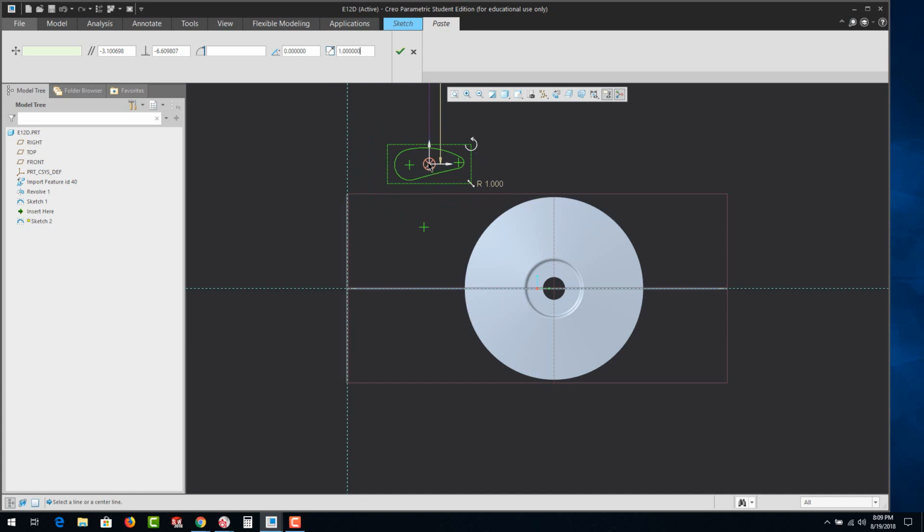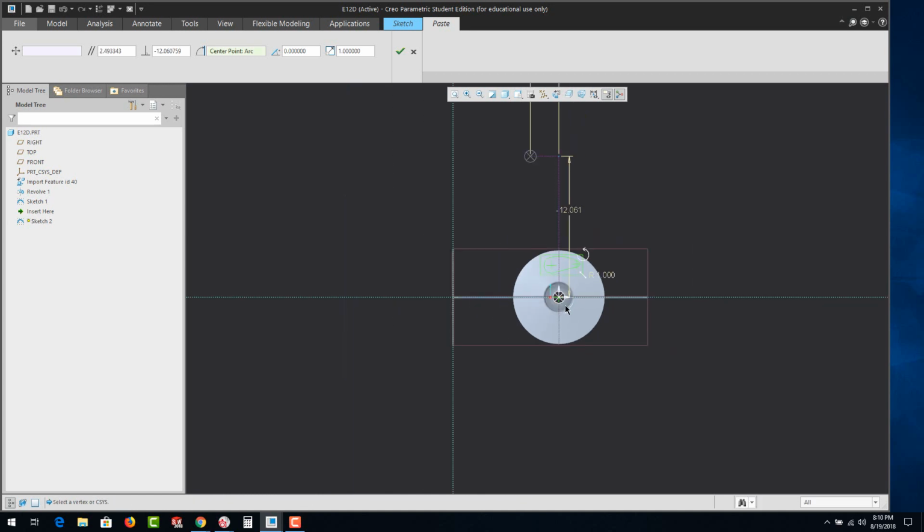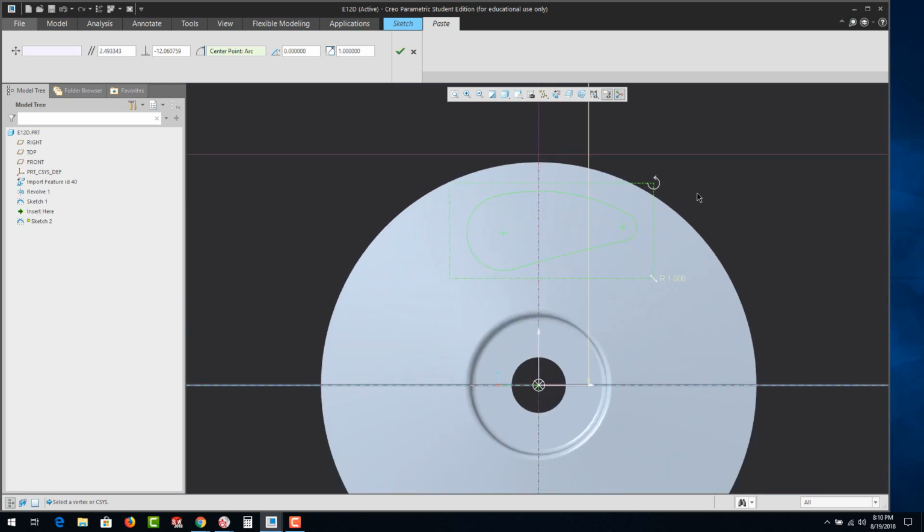And now with this little marker here, this is a really neat little tool. Hover over it, then hold your right mouse button and drag it and snap it to this little green dot here. That cross is actually the point for the top arc. Now we could drag this down with just the ordinary left mouse button, get it to the center and release it, and it should snap to it. And that's it. We now have it in position.